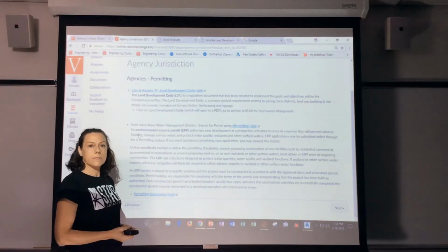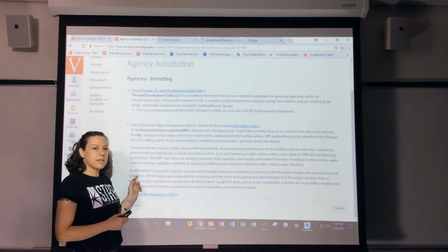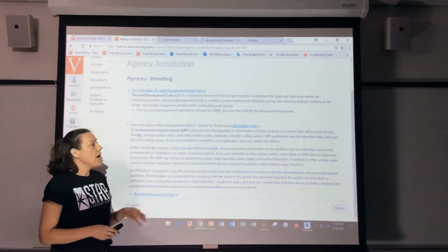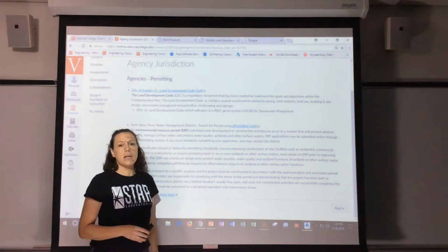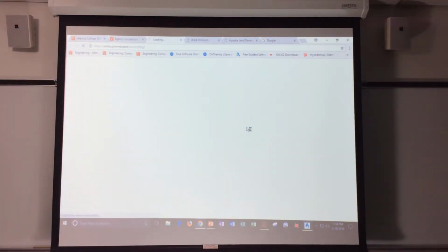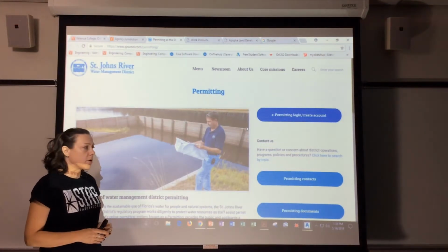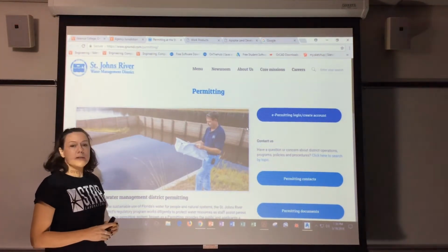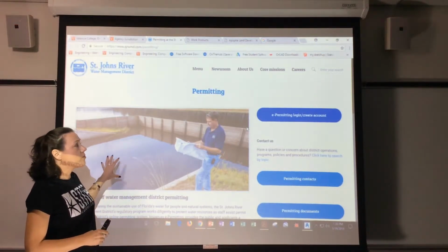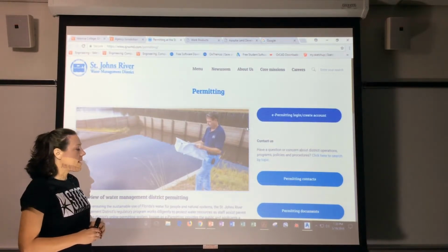Okay? All right. One thing that I forgot to mention about permitting, here's the second hyperlink for the St. John's Water Management District. I'm going to click on the e-permitting link and hopefully it'll take you to what we call an environmental resources permit, which is what we'll need. That means all projects that have stormwater ponds or storm systems typically require a permit through the water management districts.